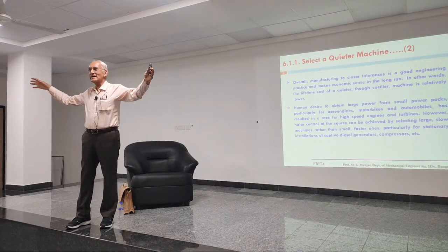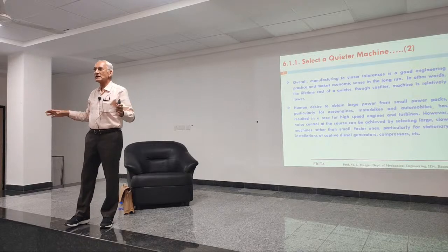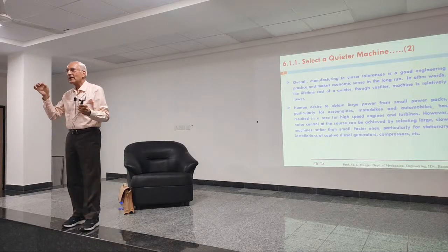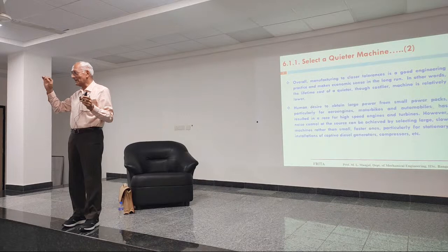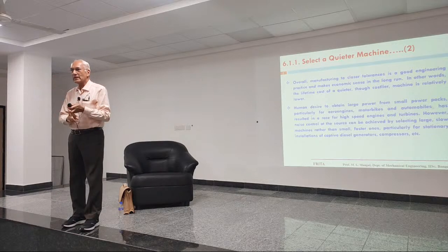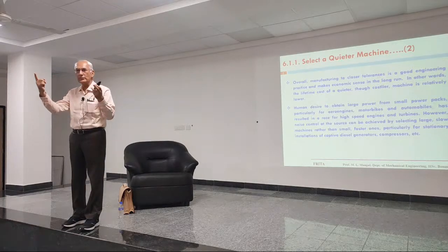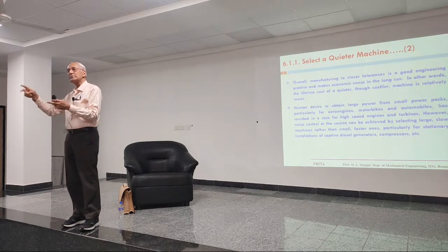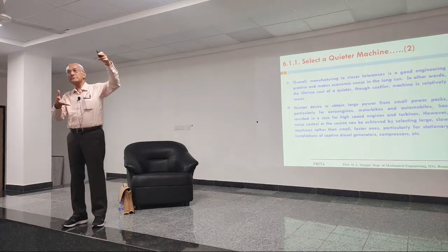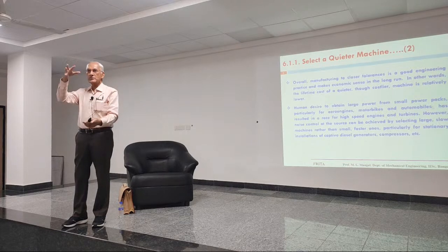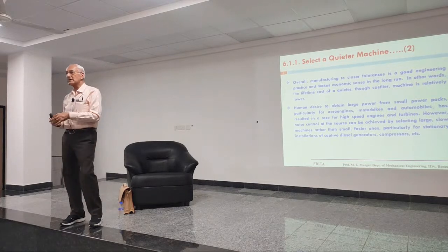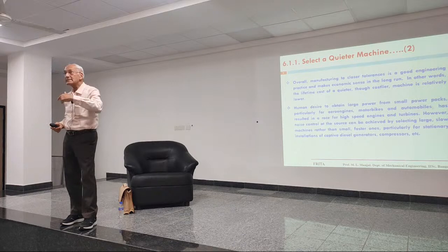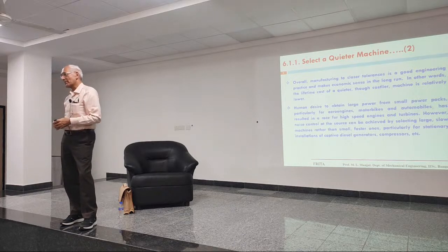He says, this is the engine that I have been using. It runs only at 125 RPM. Mind you, 125 RPM. Now, because it runs at 125 RPM, all of you know that centrifugal forces are proportional to omega square. It means proportional to speed square. And because speed is now 1/10 of normal, those inertial forces will be 1/100 of what they are otherwise.